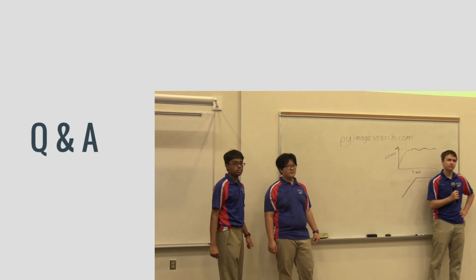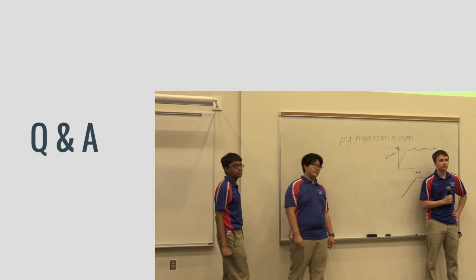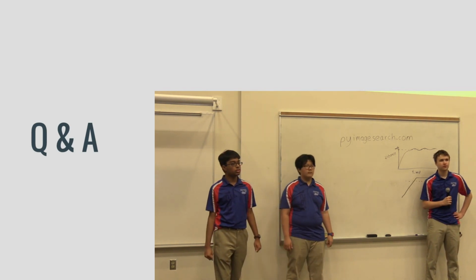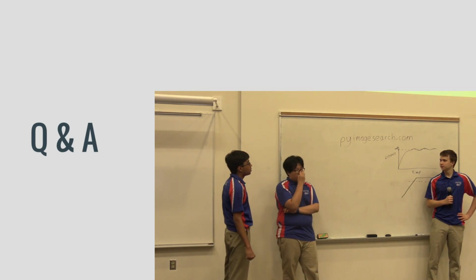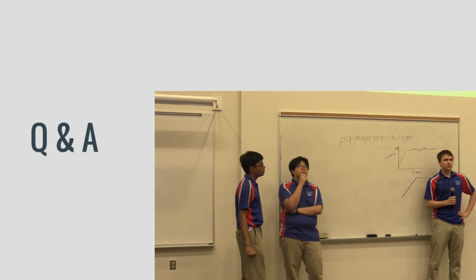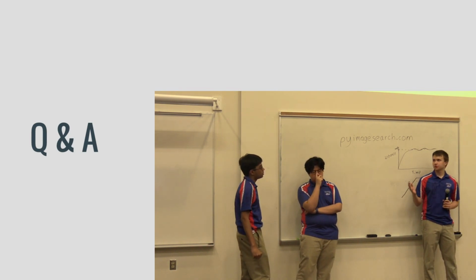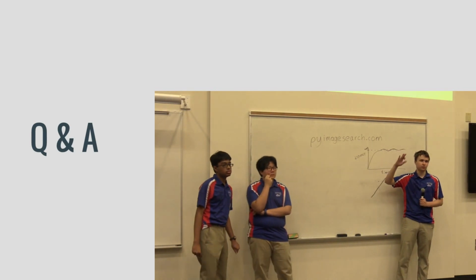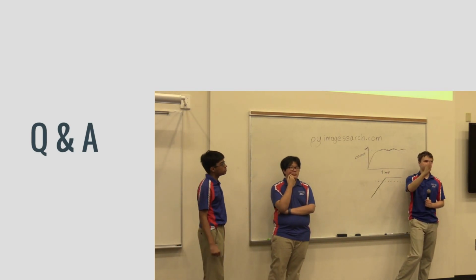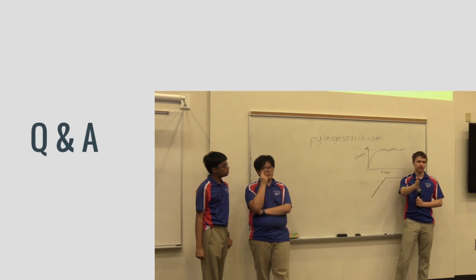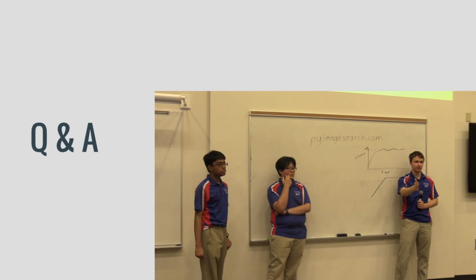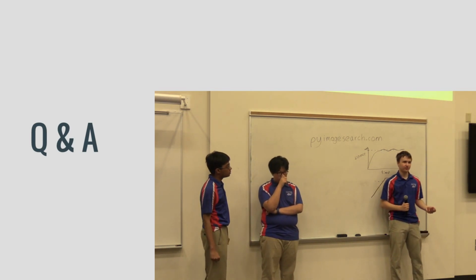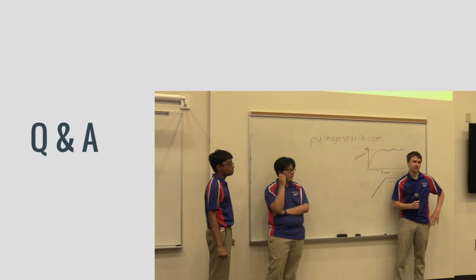Did you ever have to account for shooting, say, if you're looking at the target from an angle, a change in dimensions of the contour box? We did, because the way our system worked, as we showed in pseudocode a while ago, was we searched for the largest contour. If we were lined up between two targets, we'd sometimes have issues where it would move to aim at one, and then the other one became larger, and it would go back and forth between them. So we had to work that out. We tried to avoid those kinds of angled shots, though, because they were a very difficult edge case.